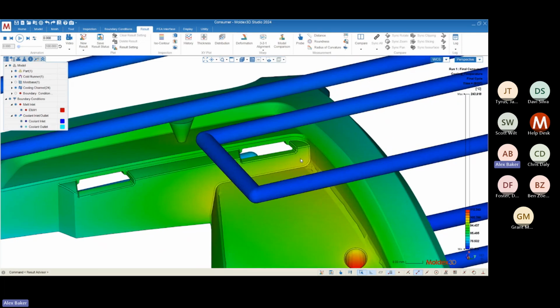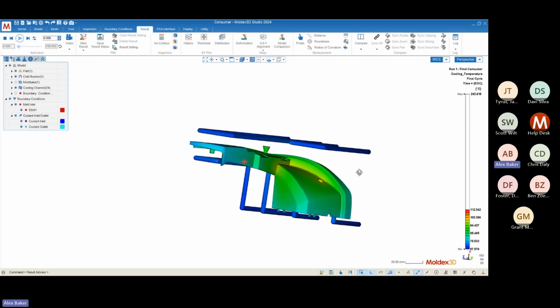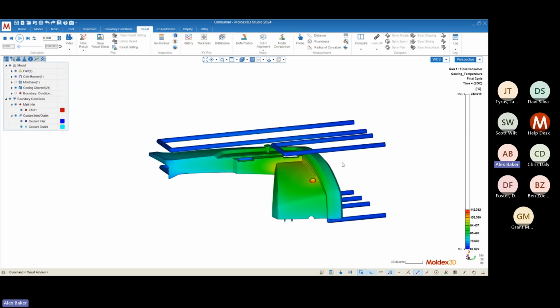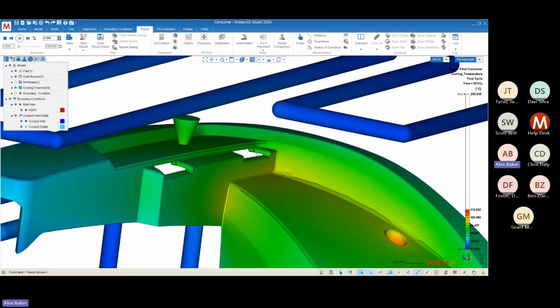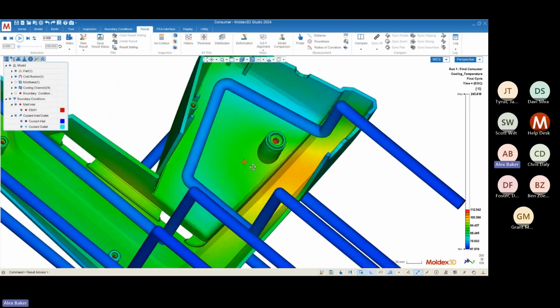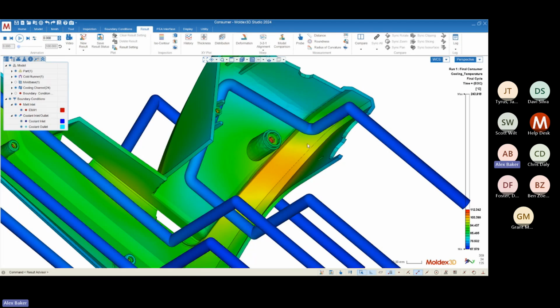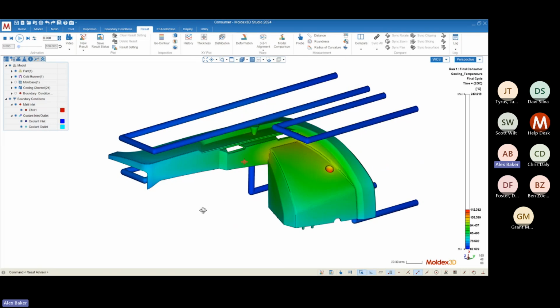And the same thing actually occurs right in here. You can see that there's a little pocket or a little corner where the heat can accumulate, and the cooling channel that I've created here does not directly address that pocket. All right, so to improve this cooling system, maybe I just drop this cooling channel a little bit closer to the surface of the part. Not sure how possible that actually is because of the actions that might be necessary for windows or these clips on the geometry. This guy I might be able to create a baffle, or maybe put in an insert that has a higher thermal conductivity to remove that heat a little bit quicker, or with a higher efficiency. These are different cooling tactics that you could look toward.